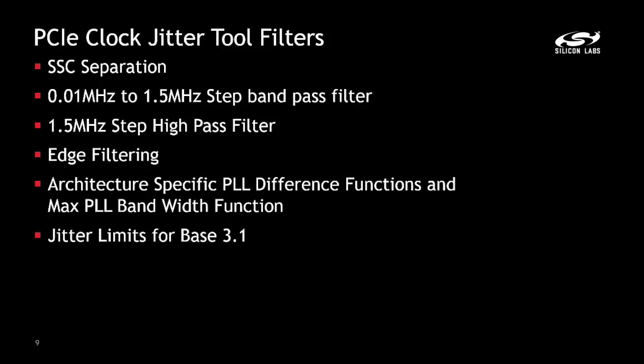The 1.5 MHz step high-pass filter completely removes the low-frequency jitter components, taking into account the high-frequency components that may or may not be tracked by the CDR. This jitter will be the dominant jitter seen by the CDR latch, causing system performance degradation.